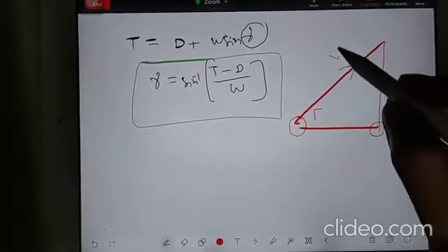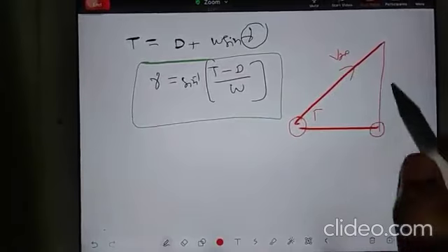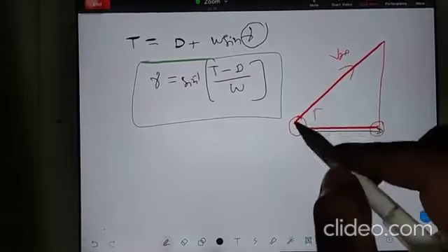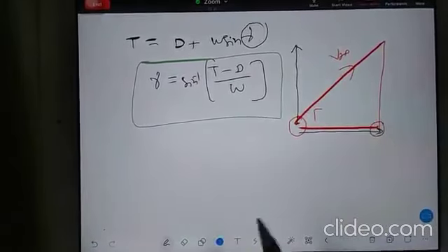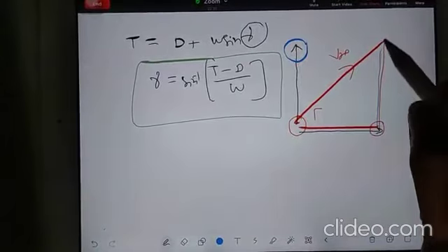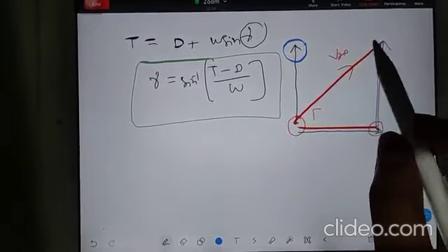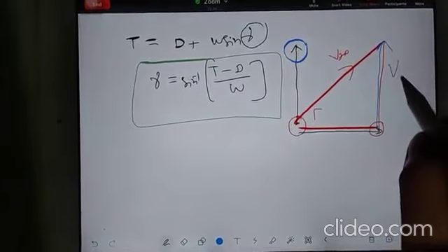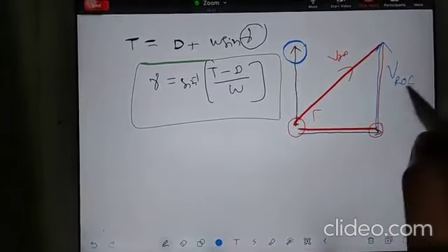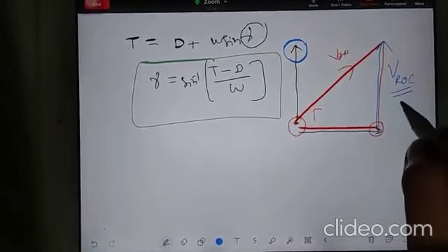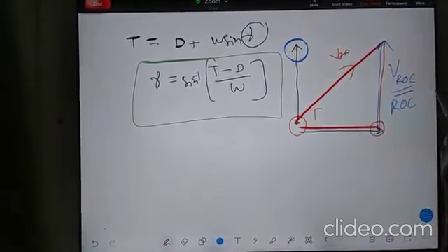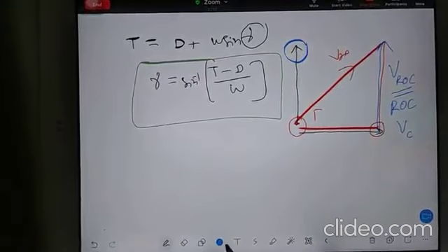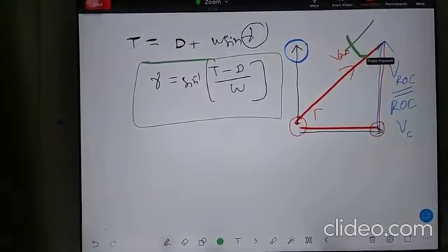I was going in this direction with free stream velocity V infinity. Then this velocity will have two components. One component will be in this direction and one component will be in the upward direction. This upward component I am drawing here is taking the aircraft up. So this component I will call V ROC, rate of climb. Sometimes you can say only ROC, sometimes VC. These are the symbols for rate of climb.